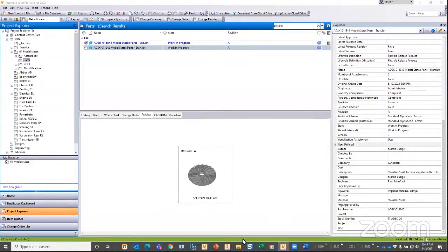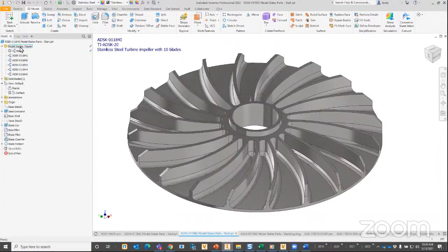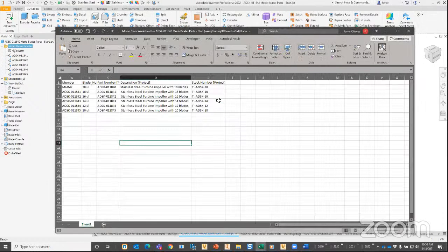So a workaround for that could be the following. If you go into the model itself and you edit the spreadsheet, it's going to probably ask me to make some changes, but it only reads this first one, and that's it. Okay, so a workaround for that could be either creating another property that captures all the part numbers, maybe separated by a comma, and that would work, right?